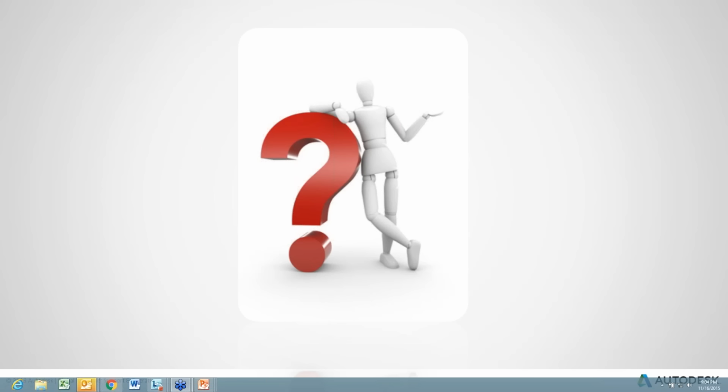The next question that we have is, after the installation of a standalone product, shall I convert it to a network license? Yes, you can, depending on the software that you're referring to. AutoCAD, yes, we have a registry entry that you can go and change. Even though we don't support it, we recommend that you uninstall and reinstall as network, but you are able to change it from standalone to network if you need to. You just need to go through extra steps to point the software to a server by creating a license linkpath.lic file that points to the server.